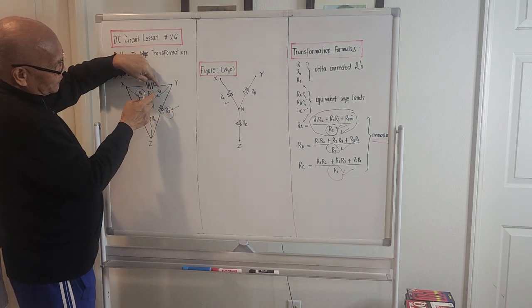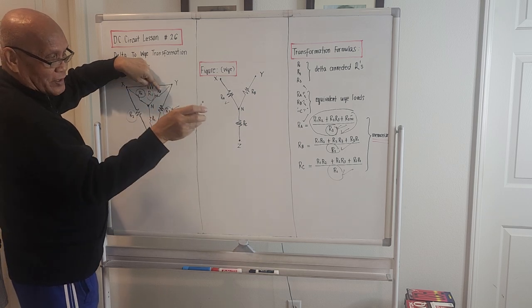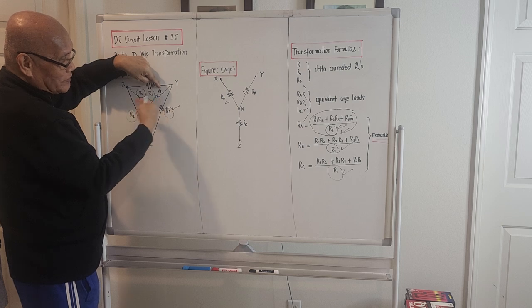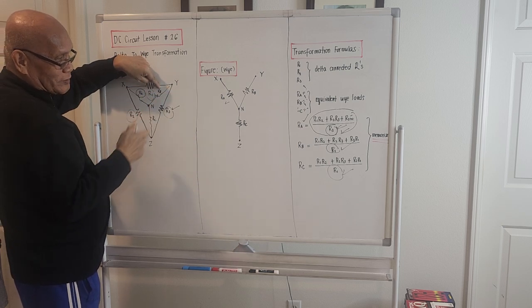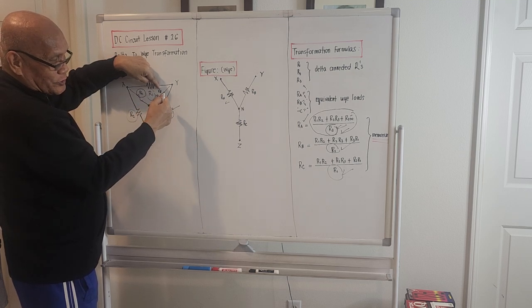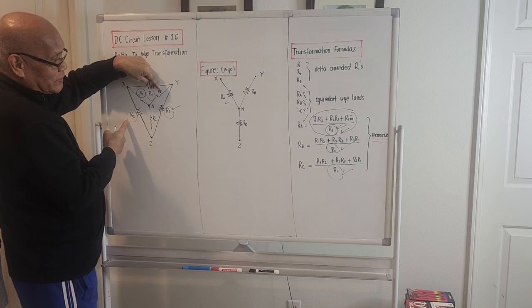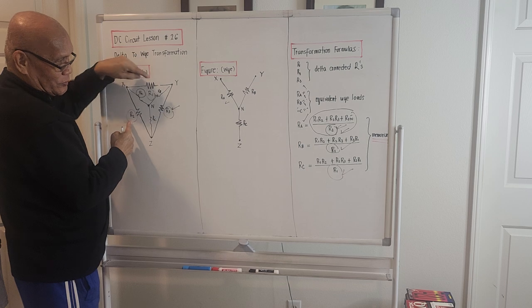If we try to compute for R sub B, the denominator should be the resistance opposite to R sub B, opposite, see in this direction. That was connected in delta. So if this is R sub B, its opposite resistance considering the delta connection is actually R sub 2. So for R sub B, the denominator should be R sub 2.